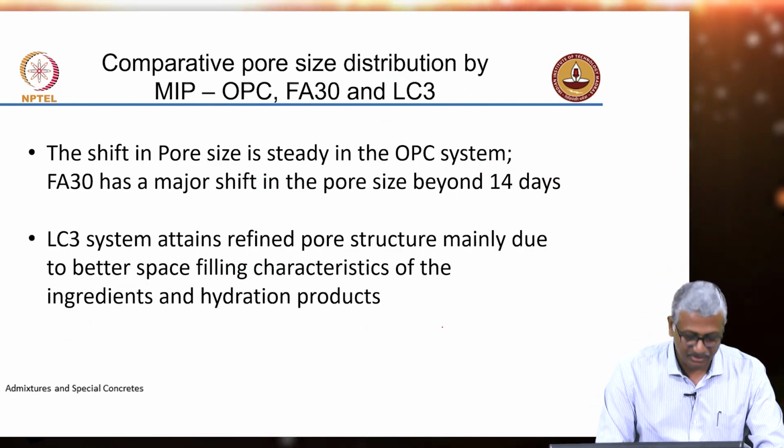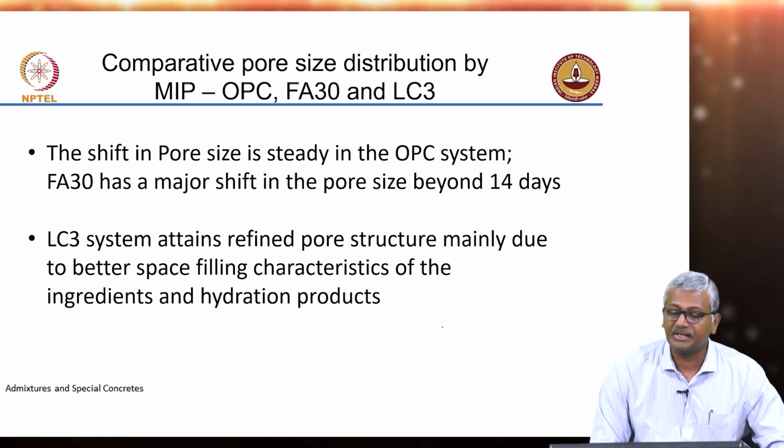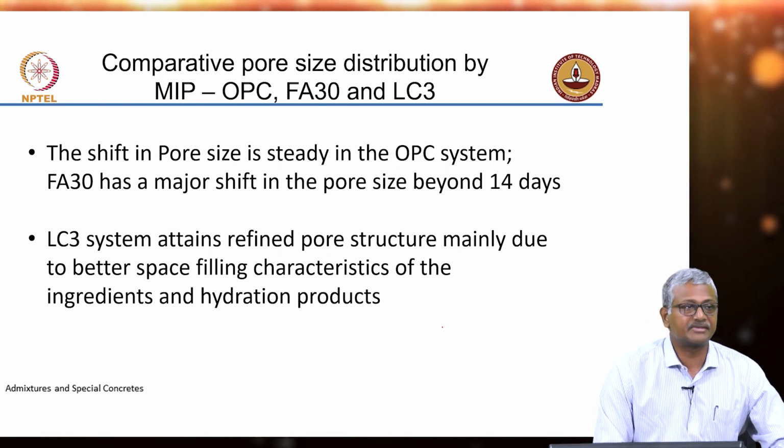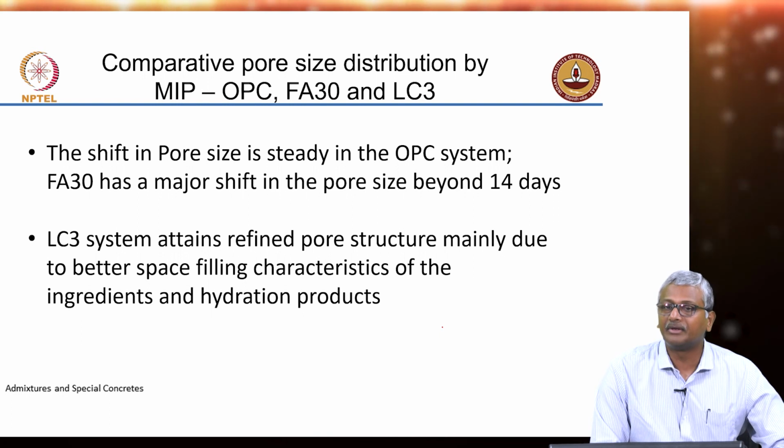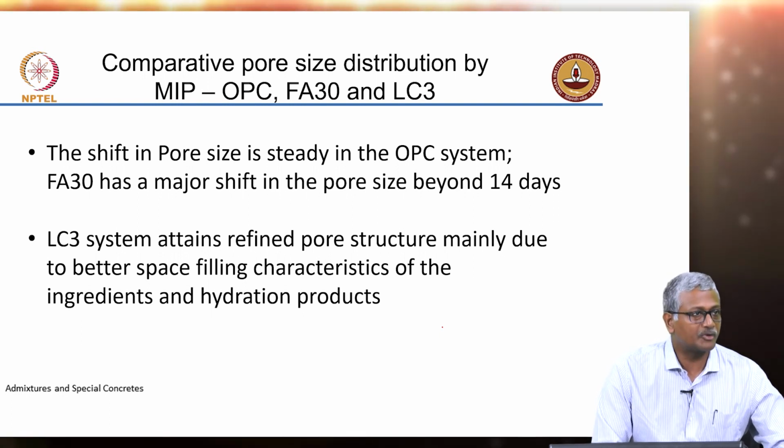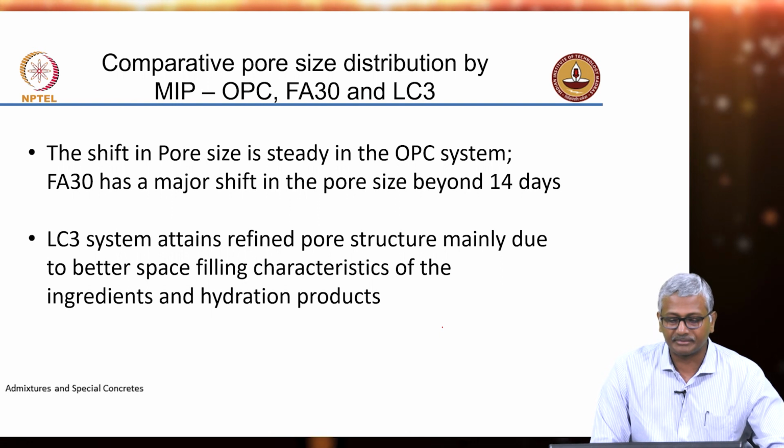Okay. So, as I said, shift in pore size is quite steady in the OPC system, whereas the fly ash system only starts moving beyond 14 days, where it gets sufficient pozzolanic activity from the fly ash.